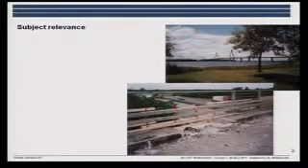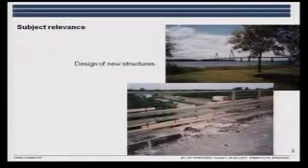So, what do we use this information on porosity and moisture fixation for? Yes, we need it for design of new structures. This is the Faro bridges in Denmark, and that was the first time that fly ash was used for a structure. It was also the first time when they used curing technology. That means that they were controlling the temperature of the concrete to limit the cracking and to limit too high temperatures. You saw in the first lecture, or the lectures on Monday, that the temperature has an impact on the porosity. So there's a certain maximum temperature the concrete must undertake in the structure.